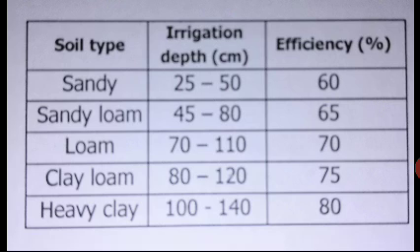Fifth one, water cools the soil and the atmosphere and thus makes more favorable environment for healthy plant growth. Sixth point, irrigation water with controlled supplies washes out or dilutes salts in the soil. Seventh one, it reduces the hazard of soil piping. Eighth one, it softens the tillage pans.